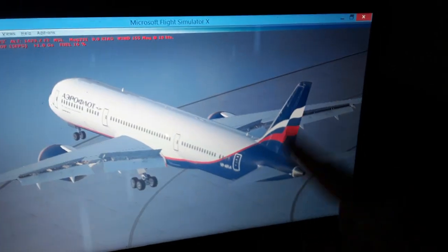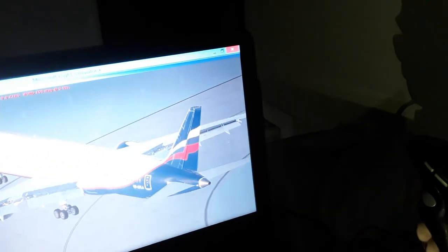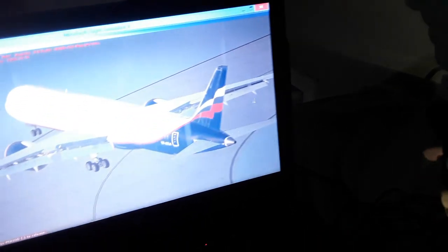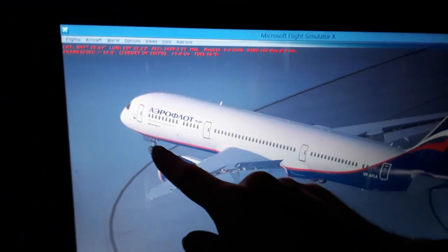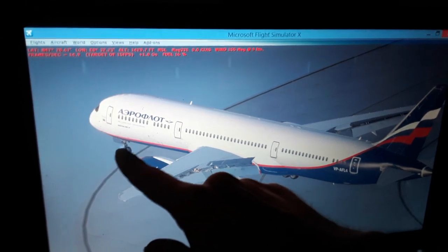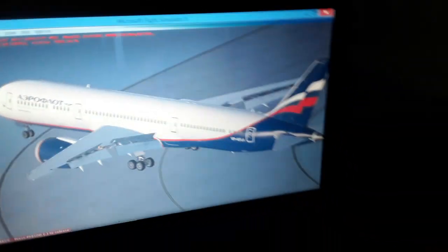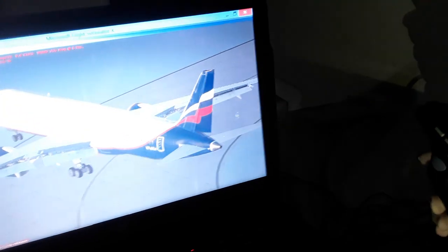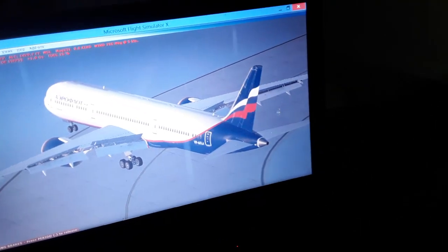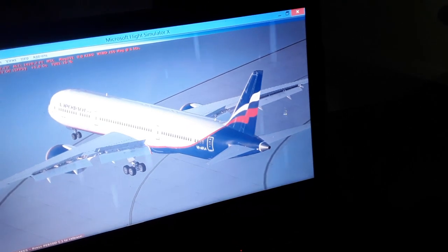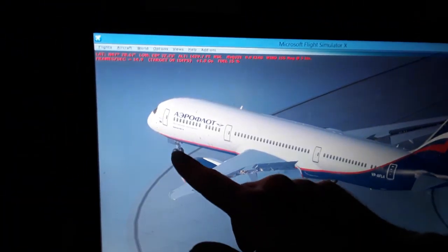And we have the rudder also a little bit aerodynamically effective, becoming so above 45 knots, when the computer decreases the deflection automatically of the forward nose wheel from 76 degrees to like 7.6 degrees left and right. We have the aerodynamic effectiveness of the rudder above 45 knots or 72 kilometers an hour.